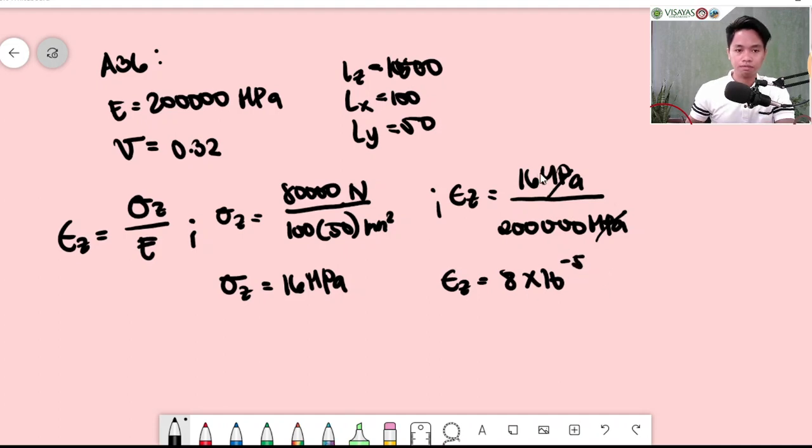So, that is positive, because it is tensile. Our stress derivative is positive. If it is a compressive force, it would be negative, but if it is a tensile force, then positive. So, since it is positive, this is an elongation.